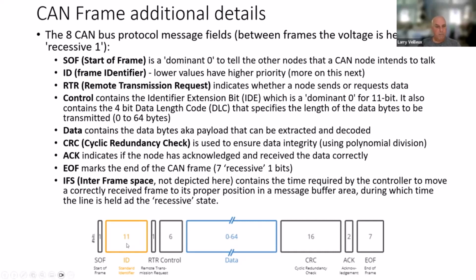The next bit that's coming is the first bit of the ID, and that's the frame identifier. One of the main things of the frame identifier is to determine the priority of the message, and that also determines who gets to keep sending if 2 send simultaneously. How likely is it that 2 will send simultaneously? Well, it just depends on how many ECUs and the speed of the medium and all that kind of stuff, and I've got a slide that talks about some of that as well. We'll get more on how that arbitration works, remember, the ID is also referred to as the arbitration field, with the prioritizations and all that.